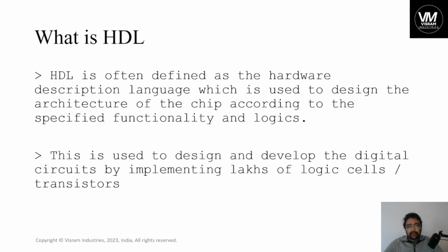Performance should be very high, like processing speed should be high. How do we achieve speed? By designing the clock. The operations inside the chip happen through logic cells, and there shouldn't be any delay. So we should give constraints on the maximum delay path, the setup path, the hold path.